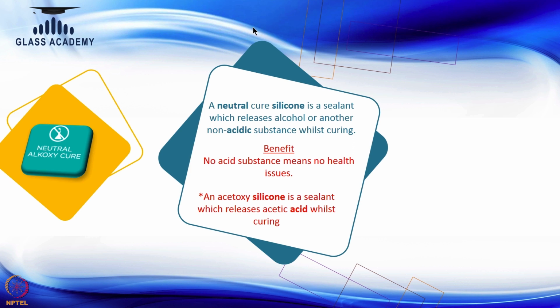So, the recommendation here, considering VOC compliance, is that we must use silicone which is of neutral base, or that category or grade known as alkoxy. One is acetoxy, which is going to emit acids; the other is alkoxy, which basically emits an alcohol based smell, which is not that long lasting. It will disappear in a period of time and there is no hazardous impact on our interiors, I mean the atmospheric air. So, the recommendation here is we should use alkoxy silicones.